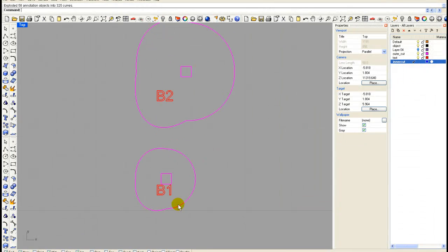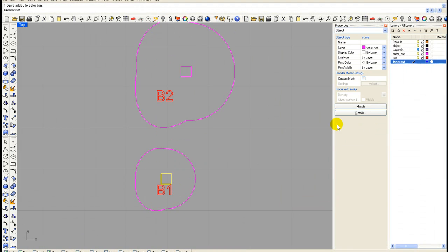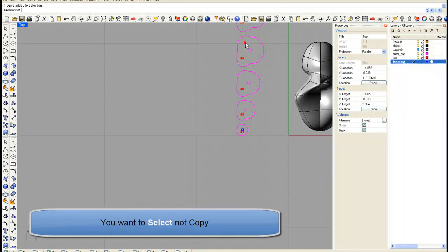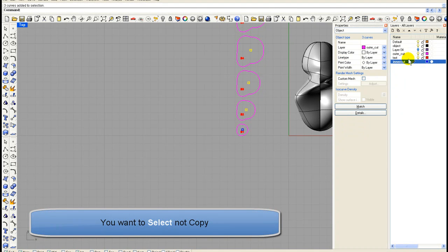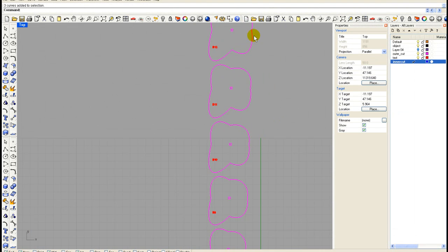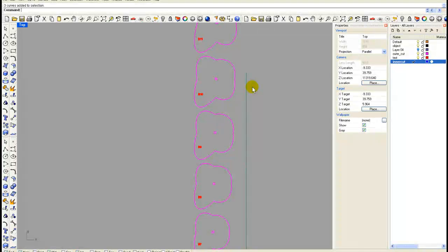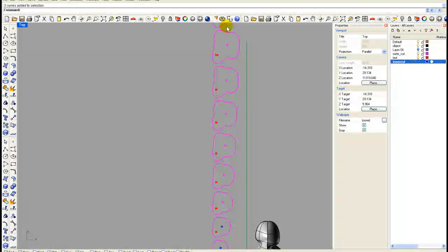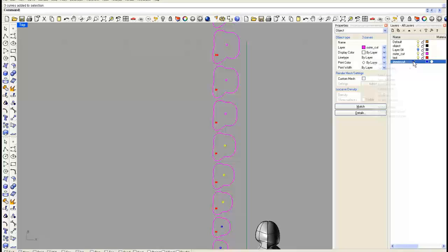And what you'll want to do is copy those and change the object layer so that those go blue. You come in here and select these like so, and you do a change object layer, make those go blue. And you always want to sweep, in this case, to do these, you want to lay these out, because now we're in the layout phase of our modeling. You want to select those and you want to change the object layer.